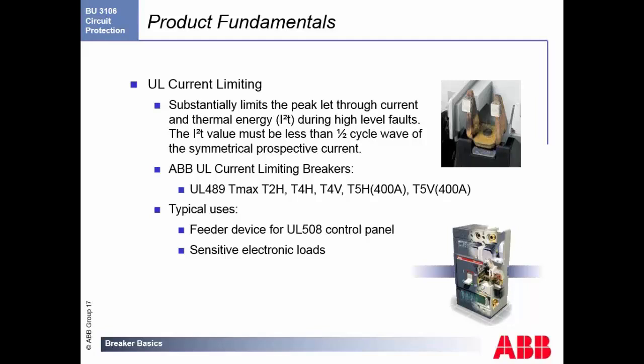Typically, our breakers do it in a quarter cycle, which is usually a little bit better than the industry average. So we do limit that current, we limit that energy, we cause more safety down the line. ABB has UL current limiting breakers in the T-Max and soon to be the T-Max XT breakers.